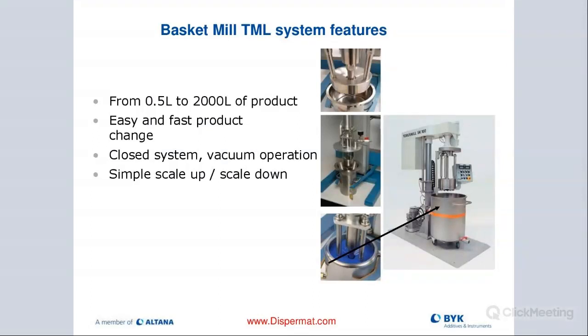This is one of the larger systems for manufacturing. We can also offer a vacuum system for operation. If we want to remove any air, that helps us transfer the product from one vessel to another much faster. Our milling efficiency also improves, because air bubbles act almost like tiny air mattresses. They would be buffers. By removing those, I should have a more efficient milling process. And from our lab scale with the C technology going to production, we have very good scale-up results, almost 1-to-1.